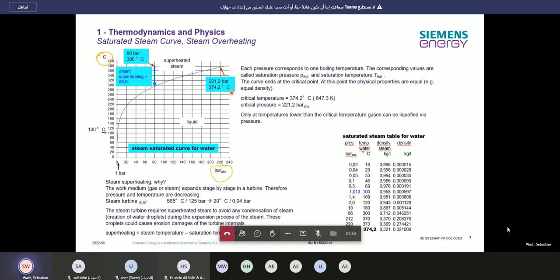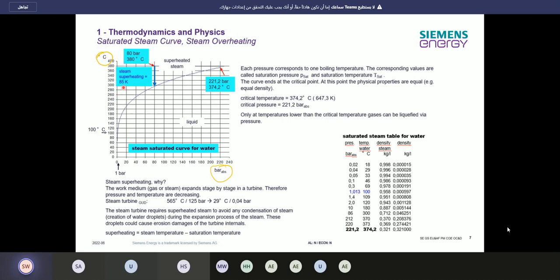As soon as it's a calculated temperature or differential temperature, like here, steam temperature, which is directly measured, and saturating temperature, which is a temperature, and you're getting a differential temperature out of it, it will be shown in Kelvin. This has the big advantage for you as an operator, when you go in there and you see, okay, I have 30 Kelvin there, so it's not a temperature of 30 Kelvin, which is then minus 240 degrees Celsius or something.